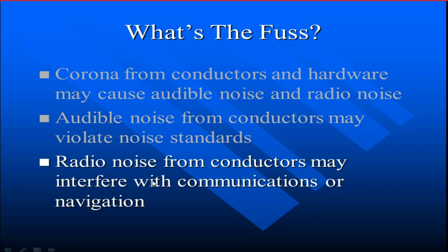Means the noise standards, as I said, we saw in yesterday's lecture, the allowable noise level at the edge of the right of way is 52 dB. But this audible noise may be greater than that, whatever limit is set for corona, and it violates the noise standard.